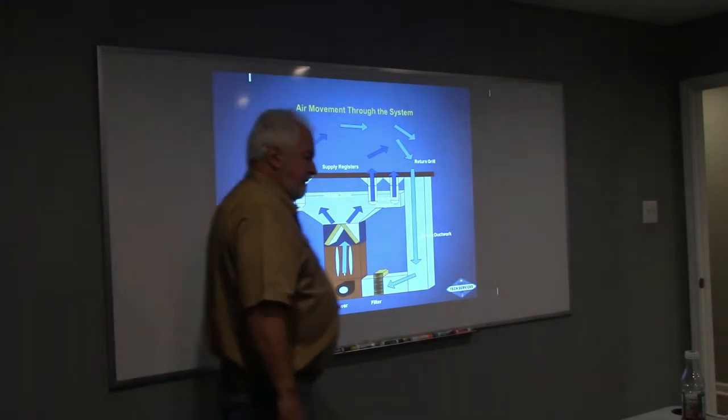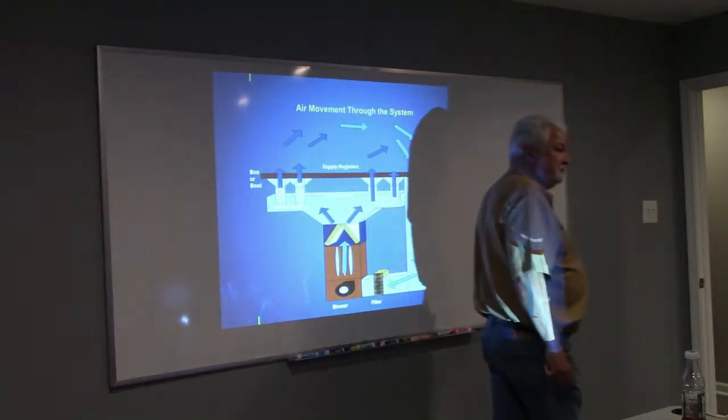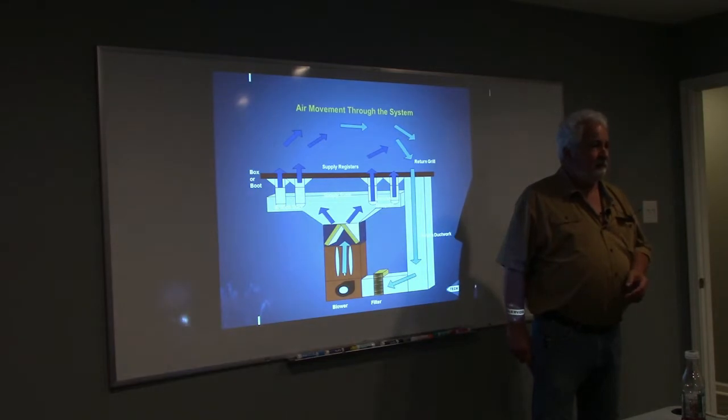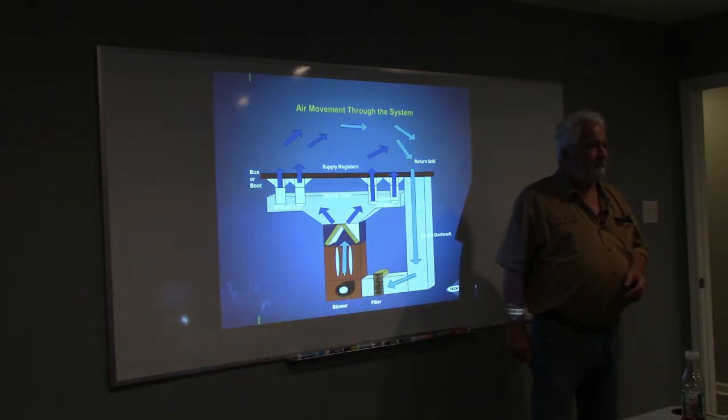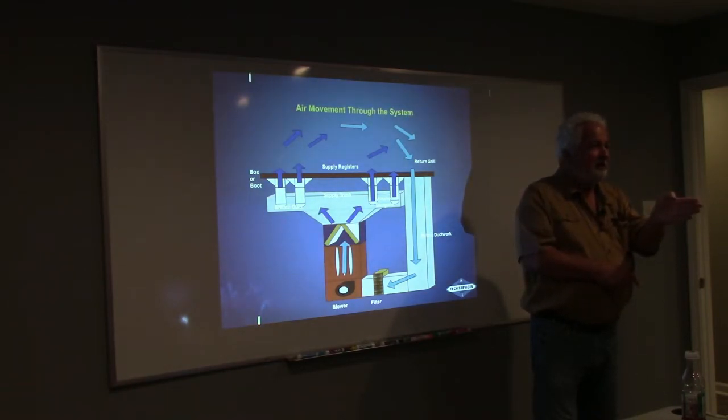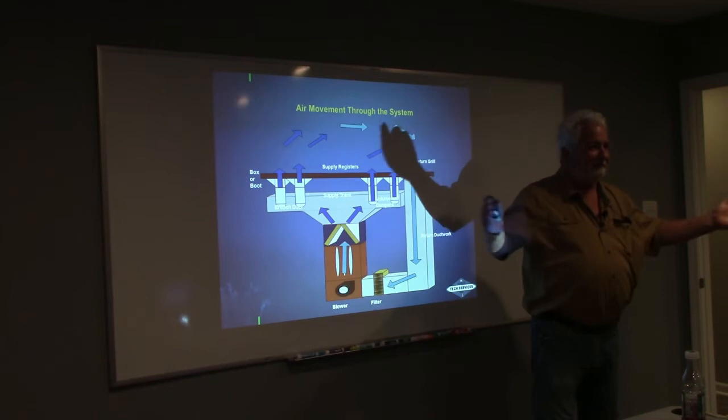But say it's an upflow, you would put your damper going that way. Good. But why wouldn't it be better to do it like this so that the damper could catch it, slowing you down? It's going to scoop it, right? Yeah, that's a scoop system. If it scoops it, how much of the duct am I using if I'm scooping it? How much, if I have static, how much of the duct am I using now? Yeah, the whole thing. I got you.